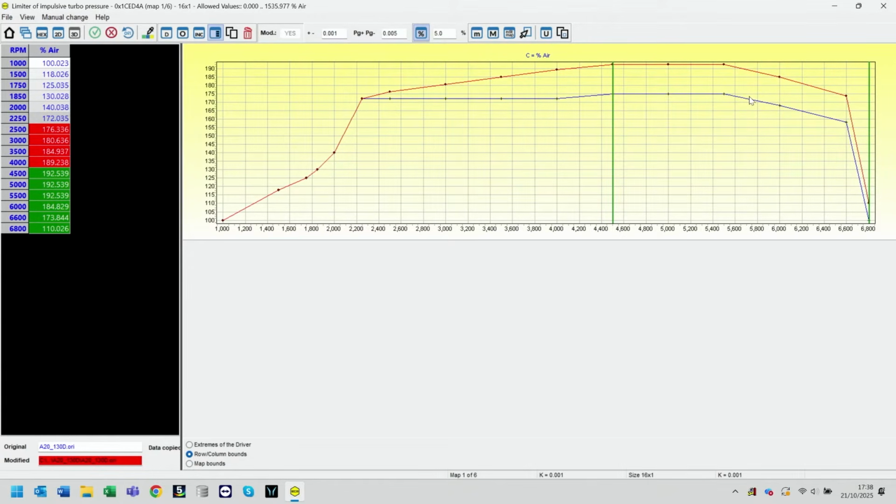Now, of course, dyno time, data logging, validate those changes, verify everything's working how you expect it to be once you've completed the tune. And if you want to push further, obviously you can. If you need to bring it back a little bit, you can as well. We often find on these vehicles, sometimes we'll actually reduce some of the stock boost low down to improve the life of the turbo, to reduce some of the wear and tear during that initial spool up. Something we do across a lot of the Volkswagen Audi group cars, even the Mark 8 Golf R, for example.